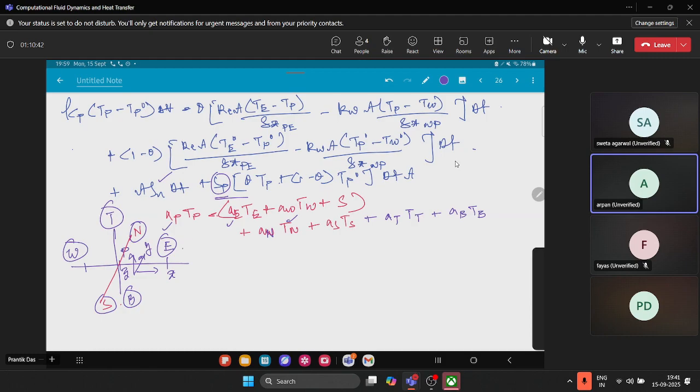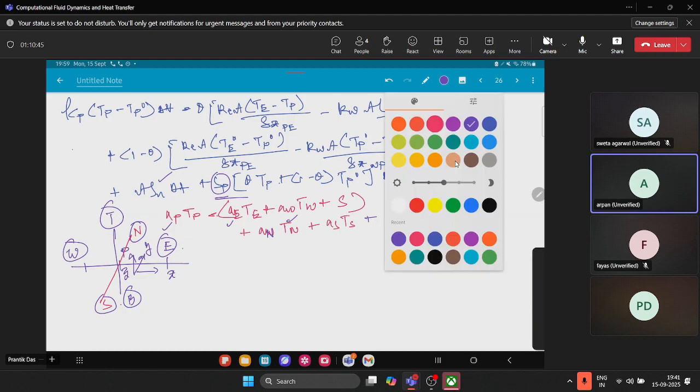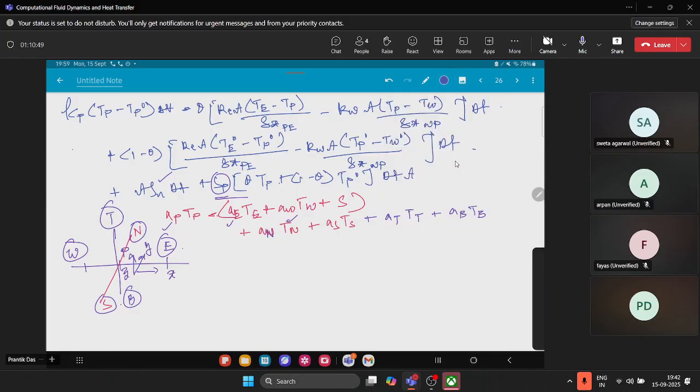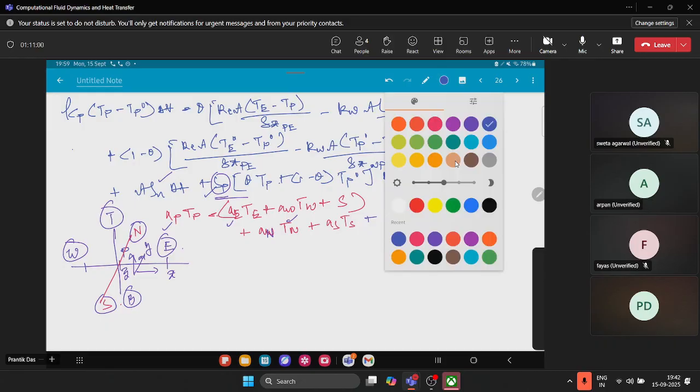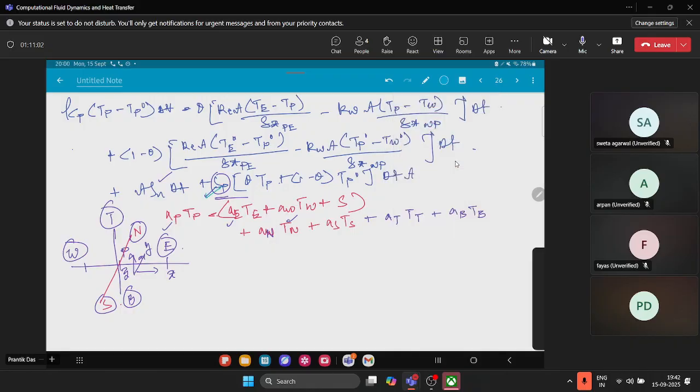It comes from the condition that the coefficient should be positive, something like that. Let me explain. I said that when you're writing the source term as SC plus SP TP, SP should be negative. Do you agree with me? So on the right hand side of the equation, this SP is there. When I'm writing this in the AX equals B format, then T is basically A inverse B.